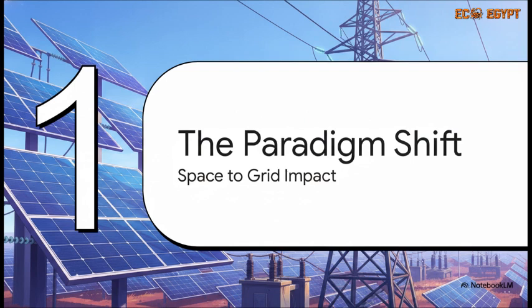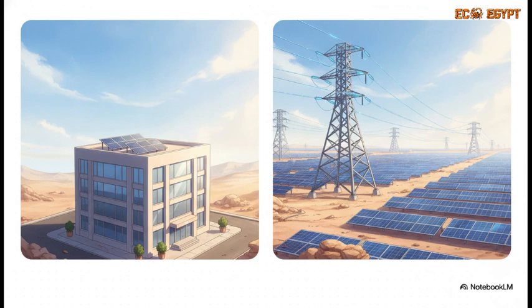Section 1. The paradigm shift, moving from available space to grid impact. To succeed at this level, you've got to fundamentally change your mindset. In C&I, or commercial and industrial scale, your workflow usually starts with the available space and figuring out what percentage of the client's bill you can cover, right? But utility scale is a whole different beast. It all starts with the client requirements and, crucially, the grid impact study. Your main concern isn't just generating power, it's defining exactly how much power the grid line can withstand without going down.